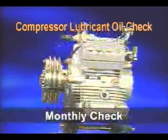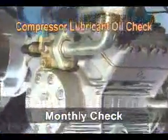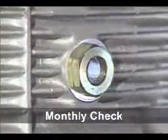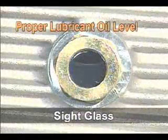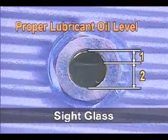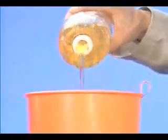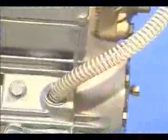Compressor lubricant oil is very important for the smooth operation of the air conditioner. Check the color and quantity of the lubricant oil every month through the sight glass. For the proper quantity, check whether the lubricant oil level positions at the 2/3 position of the sight glass. Refill the oil when it becomes low, and don't forget to check the oil level when replacing any components.